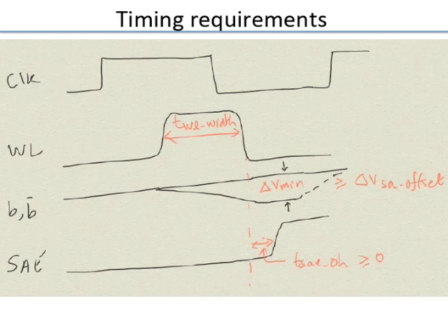Compared to that, you have one extra bit which is swinging full swing. So there is an overhead, definitely, an area overhead and power overhead, but that overhead is quite small compared to the savings you get because you are able to shut off the word lines and prevent the discharge of the bit lines.